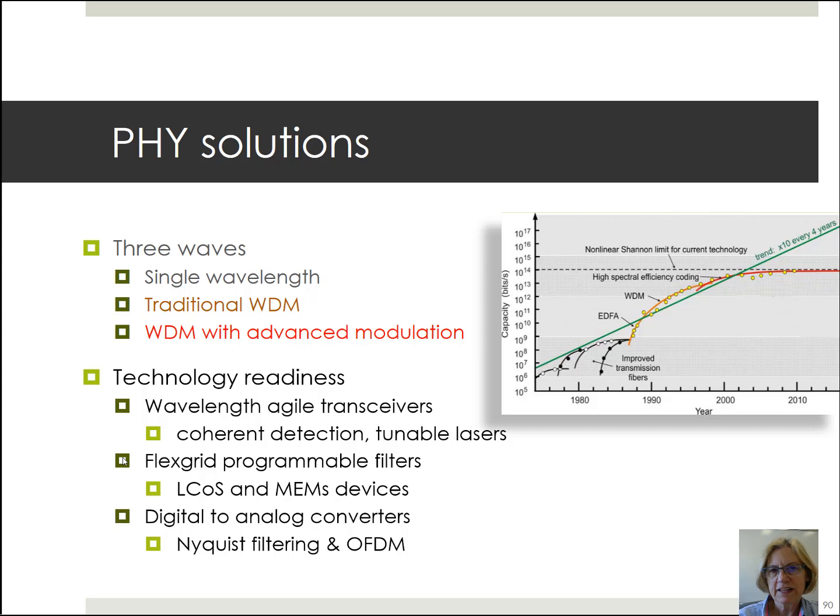We've talked very briefly, I didn't say much, but there has been work in these programmable filters. So there was a lot of interest in liquid crystal on silicon to create wavelength selective switches, which are currently used in the ROADM technology, which could also be redirected towards a Flexgrid solution.